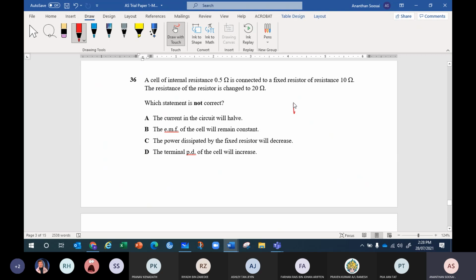Okay. So originally the battery has an internal resistance of 0.5 ohm. The load at the beginning was only 10 ohm. That means the capital R, the load, is 10 ohm, 0.5 is small r, and the voltage, we assume it has a certain EMF E. They didn't give the E. So how is this linked?